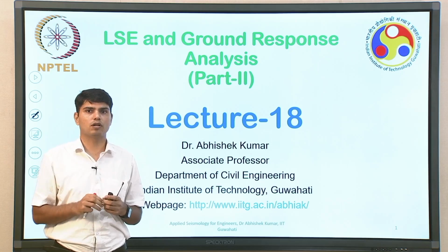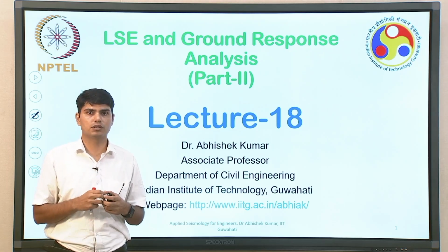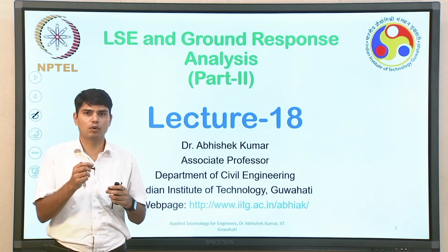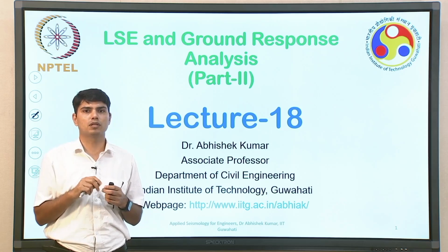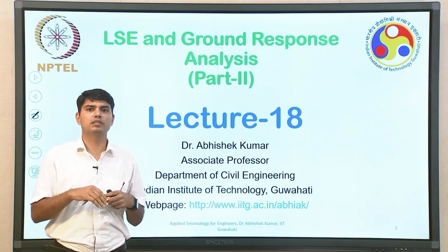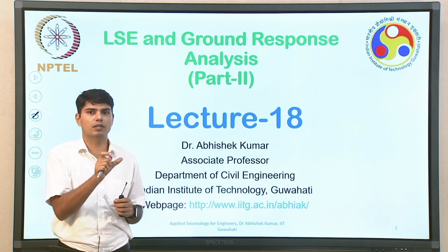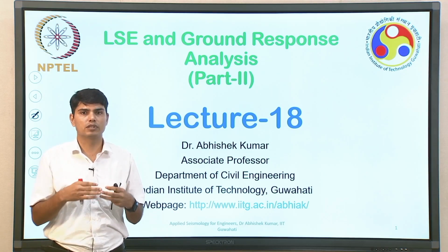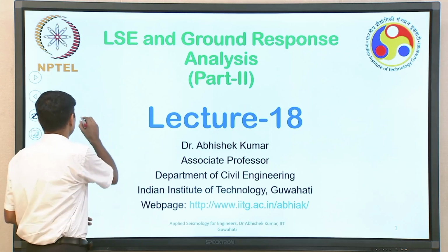So, when we say Fourier spectra of a given earthquake induced motion, we are interested to find out how many cycles of harmonic motions are present in that particular given motion. Harmonic cycles means the operating frequency of the motion as well as the amplitude of each harmonic motion is going to remain constant. So, when we say we are interested to find out the frequency content of the motion, we are interested to find out that for a given earthquake induced motion, how many samples of harmonic frequency motions are existing. So, that will be on x axis,